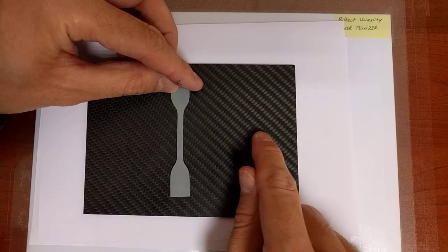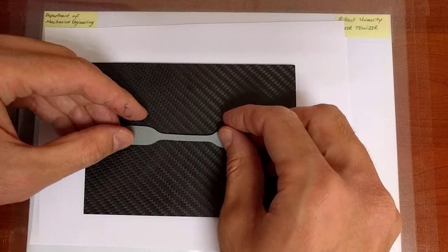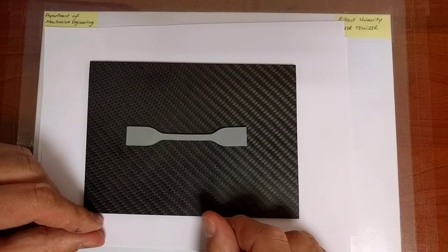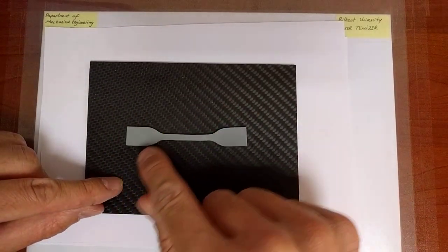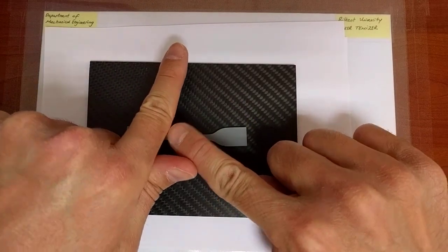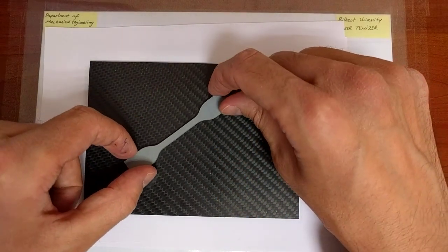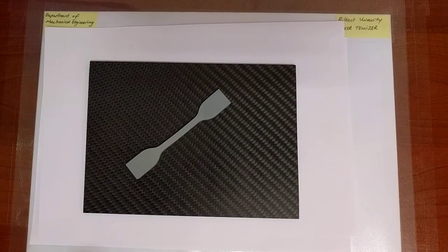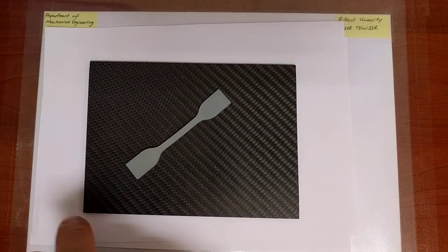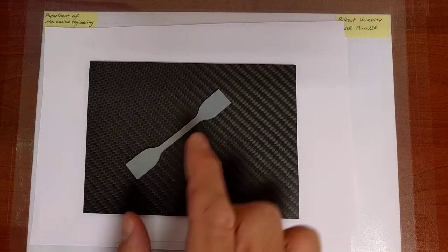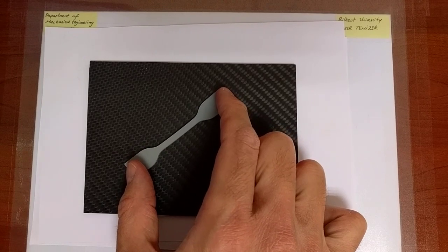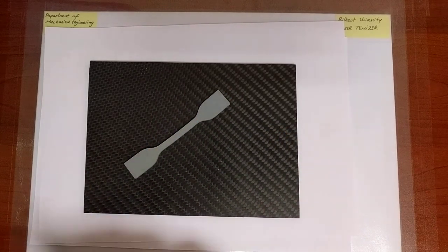And there are also fibers running in that direction. So if I cut a specimen in that direction, it will also be very strong. But there are no fibers running in the other direction, or at least I'm not going to load the specimen in the optimal direction if I cut a specimen that lies in some skewed direction. So that specimen will probably give me a strength that is less than the other two directions.